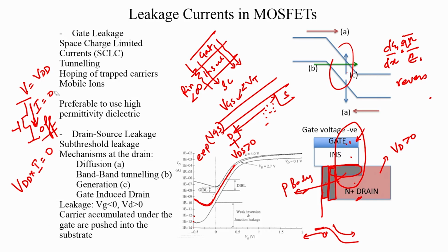But because you now have a leakage current, since I is not 0 and you have all these leakage mechanisms, you have static power consumption in a MOSFET circuit, and this power consumption exists even when all the MOSFETs are turned off, and this is going to drain the battery charge because it is going to continuously drain this much of power from the battery. It is going to drain this much of charge, this much of energy from the battery at this power.